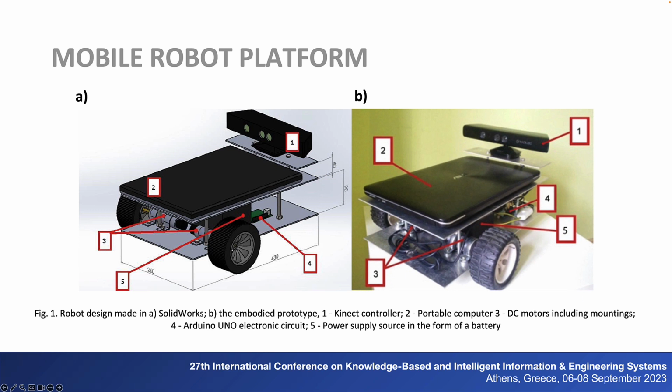An ATmega328 microcontroller available on the Arduino Uno platform was used to power the encoders located on the motors and the H-bridge circuit. The Arduino Uno chip itself is powered via USB by a laptop computer placed on the upper shelf of the robot. The Kinect controller is positioned on the back of the robot, on an elevation attached to the upper shelf. This positioning of the device will almost negate the minimum range of distance measurements to be taken.